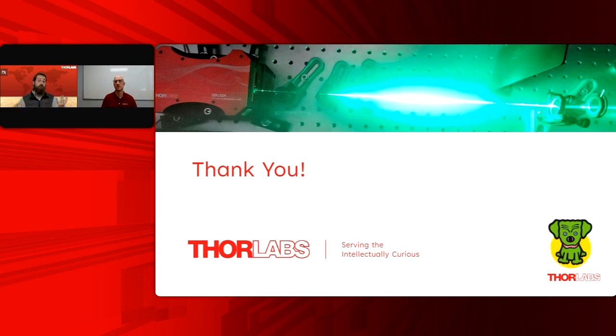However, if we had simply used, say, a 600 micron core multimode fiber, then we would have issues coupling into the spectrometer. So to get maximum efficiency coupling from the fiber to the spectrometer, you need a linear bundle. But because the distribution of plasma is not even across all of 3D space, a linear bundle will actually hurt your collection of the light at the plasma. And so that's why we use a round to linear bundle.